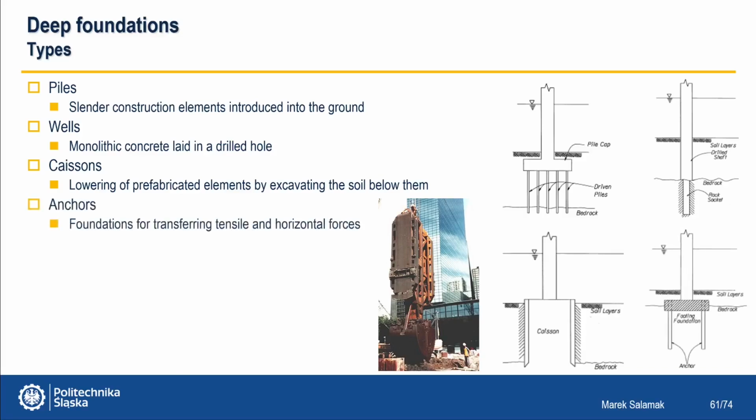We also have anchors or foundations for transferring tensile and horizontal forces. More and more often in bridges, slurry walls are also used, which consist in filling a narrow space excavation with concrete in which the reinforcement was previously placed.